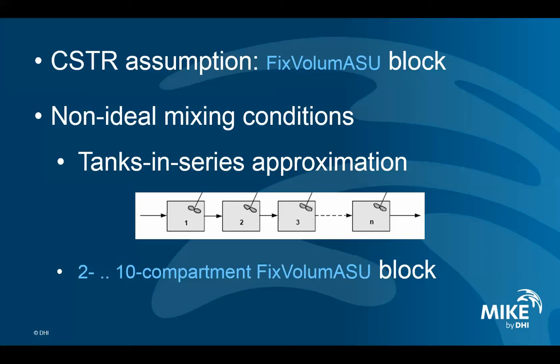But the question is now, how can I choose how many compartments are appropriate for a given situation? One way is clearly to conduct a tracer test on my real scale tank, to spike a certain amount of non-reactive soluble substance, the tracer, and to measure the recovery of that same substance at the outlet of the tank. Then to model the test and compare the measured data set with the output of the simulation. And this is what I would like to demonstrate in the video.